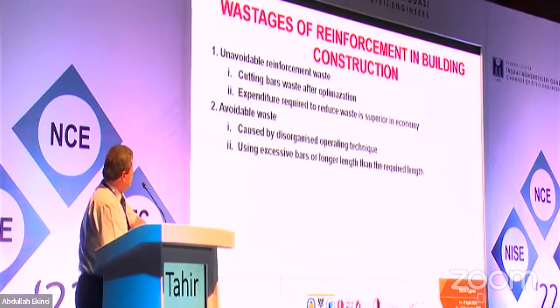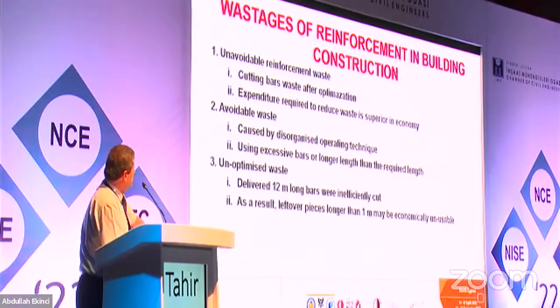Avoidable waste is caused by disorganized operating technique on the construction site, using excessive bars or longer than the required length. This is the most important part of it, probably. Unoptimized waste: delivered 12-meter long bars were ineffectively cut. This is again one of the important points I want to talk about.